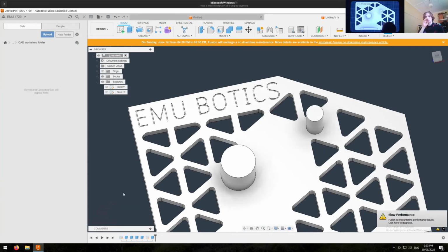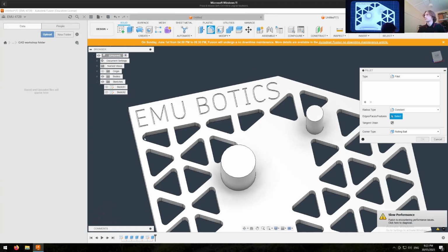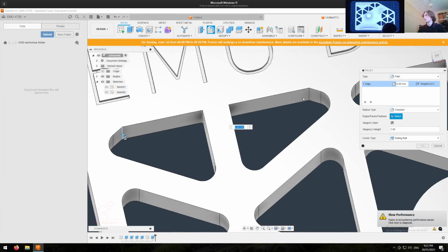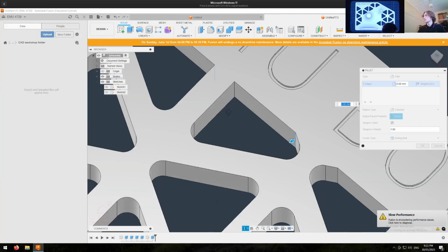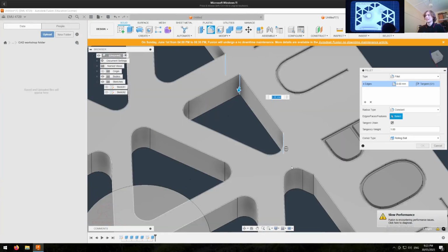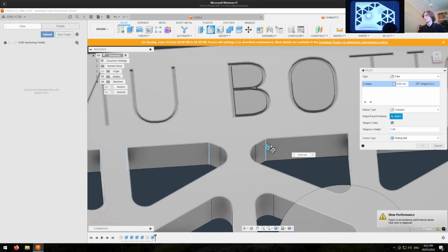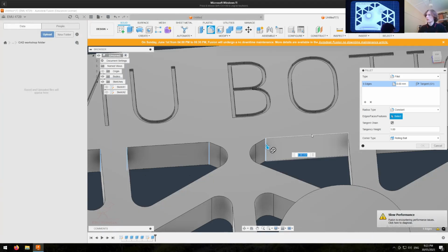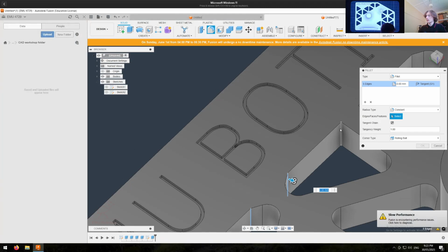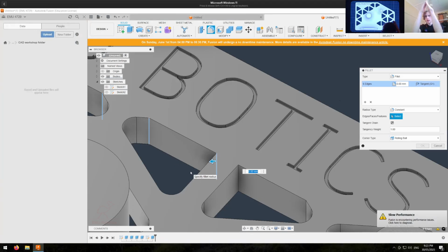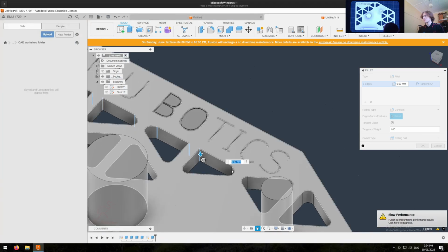Now, we can press F on our keyboard to open fillet. And then we can go in here and, oh, that's the wrong line. We just want to select these vertical lines. Specifically, we're selecting the lines where there are sharp corners. A sharp corner like this one is not going to be the end of your robot. But a sharp corner like this, a 90-degree corner, or even sharper than that, say a 30-degree one that is really tight, is going to be a stress raiser. And we do not want stress raisers on our robot.